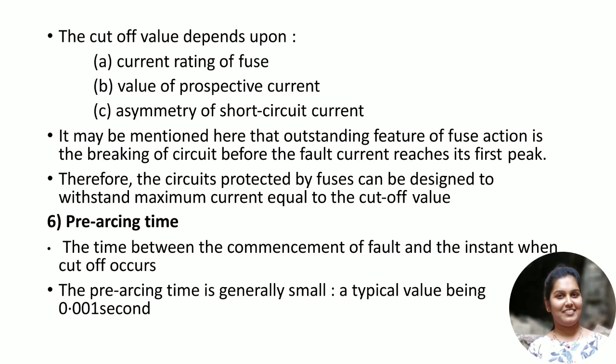So this cutoff current value depends upon three parameters, that is nothing but current rating of the fuse, the value of prospective current, and asymmetry of short circuit current. On these three factors, the cutoff current value will depend.